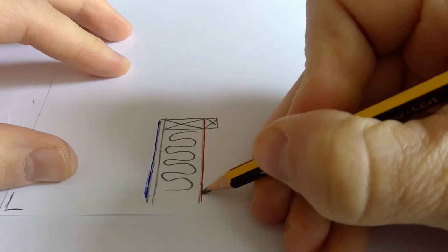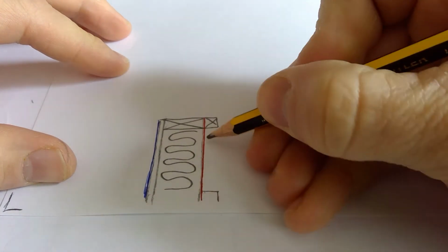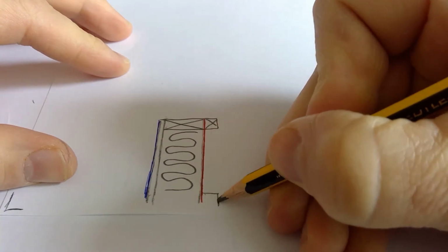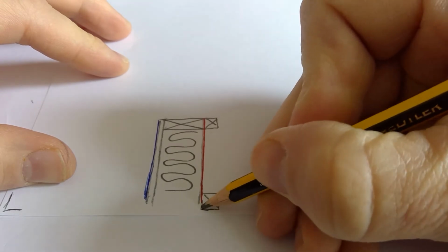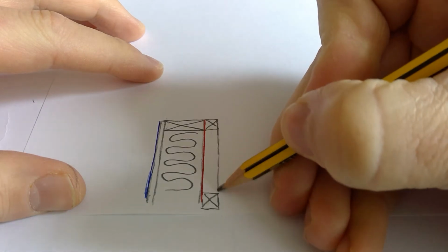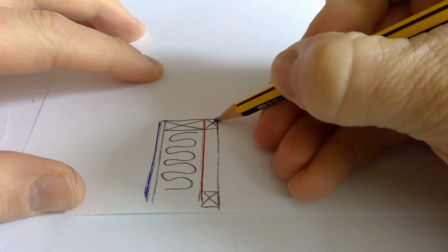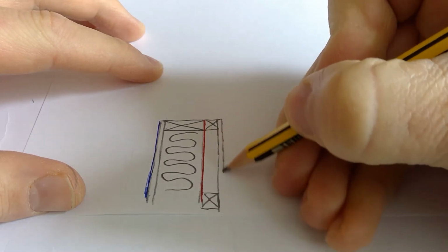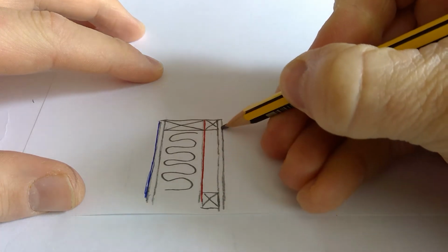Right, and maybe have one just down at the bottom as well. You can judge how far down that is yourself. Usually it'd be around 400 mil centers, but just for the sake of the drawing, if you want to get one in there, you can. And there is where the plasterboard is stuck on. So 50 mil there, and then another 12 mil plasterboard. That will give you your 60 mil service cavity.